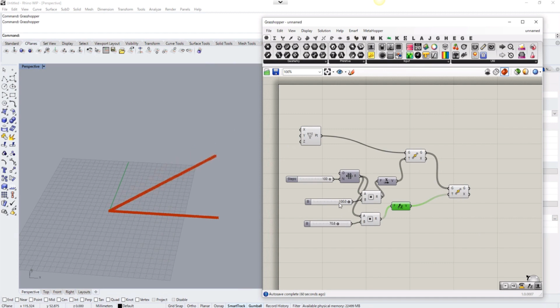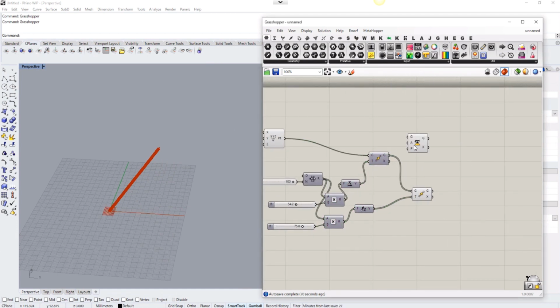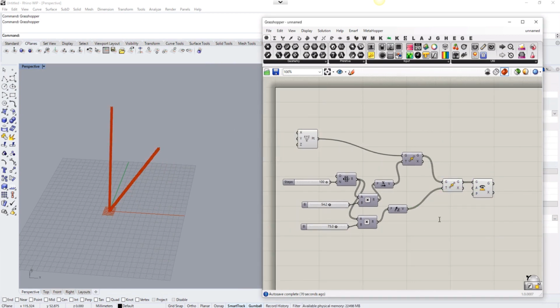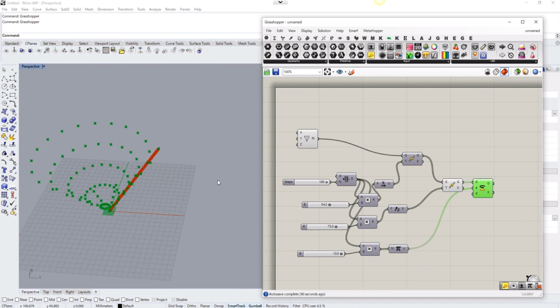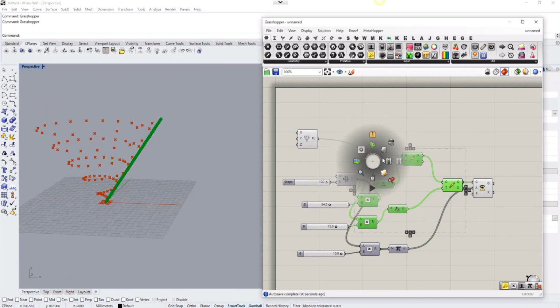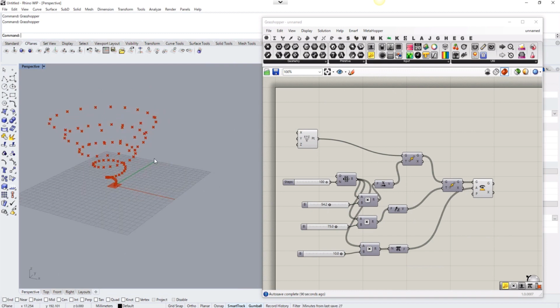Maybe change some numbers parametrically. And then rotate these points so that I can make it a spiral curve. I also need to make another value here, and maybe change the range of the sliders to a maximum of 10, and use pi and rotate, creating a rotated spiral point array like this.